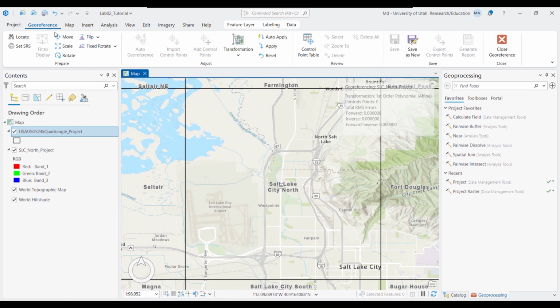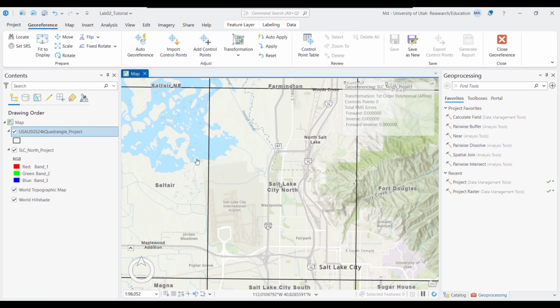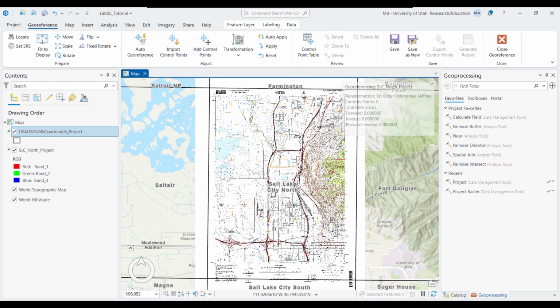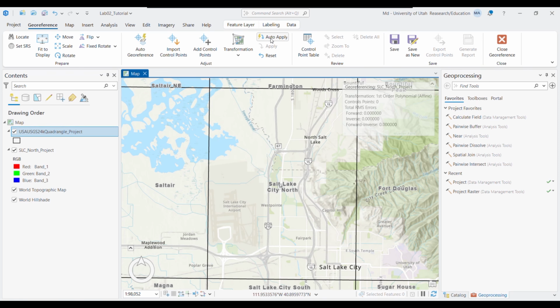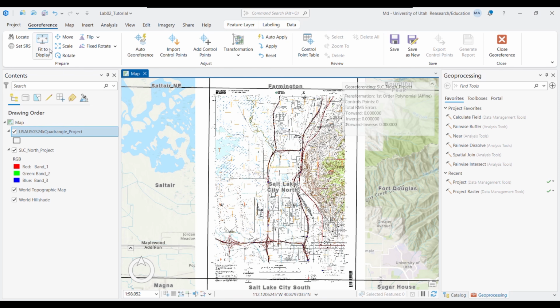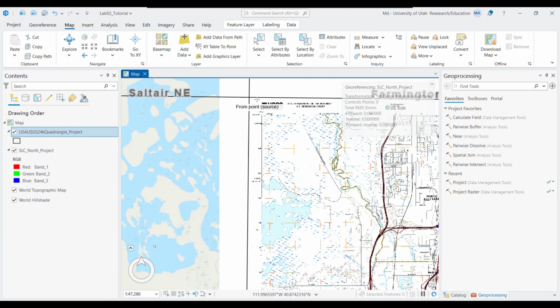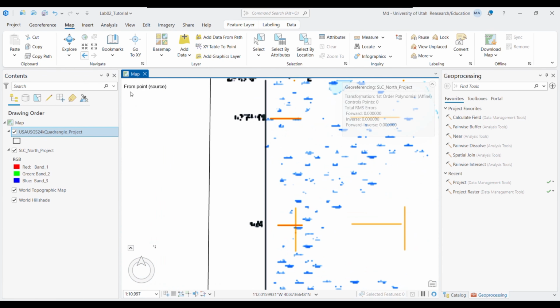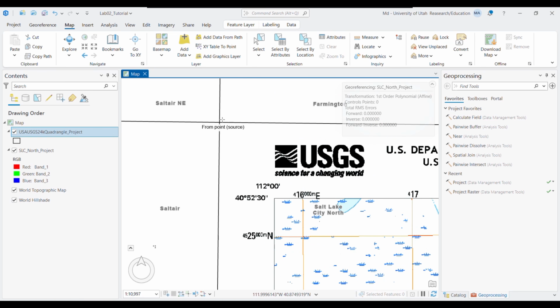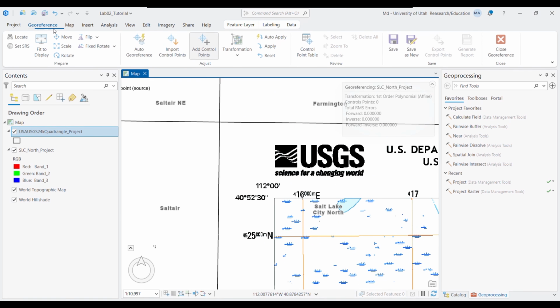We will select this and we need to click Set SRS if you see that the Fit to Display section is unavailable. If you click on Set SRS, the Fit to Display icon will become available. Just click on that and your image will appear wherever you want it to appear. So we know that we have to georeference it here. These are the corresponding points.